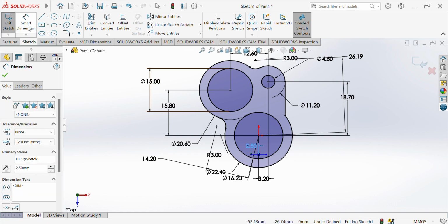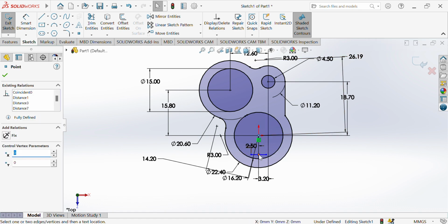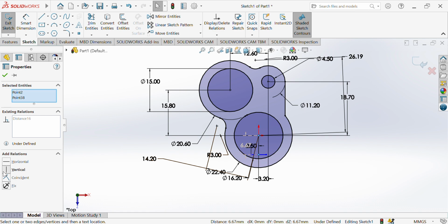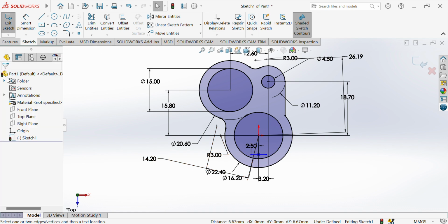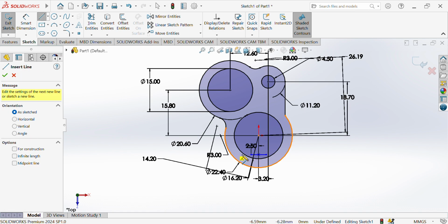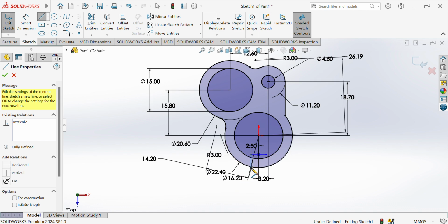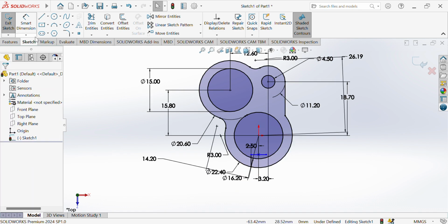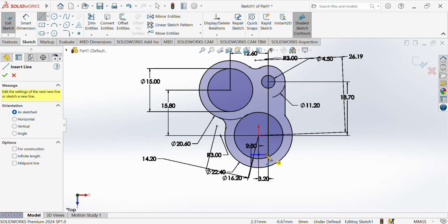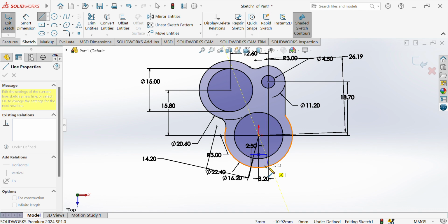Then leaving your small dimension tool, just extend straight lines from the 2 ends of the midpoint line. Let's make them vertical though. So you select the center of the drawing and hold your control key, select the center of this one and do vertical. So now they're on the same vertical axis. So use your line to just stand at the end point and draw a straight line down. Escape it. Use your line on the other side, click on it, then draw a straight line down. Make sure you see that 90 degrees, it means that it's straight.